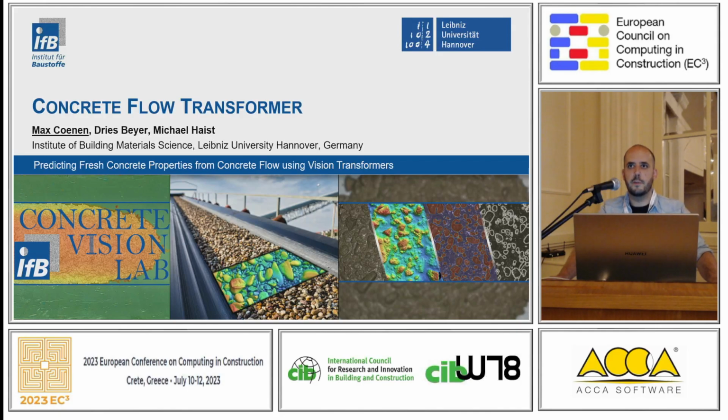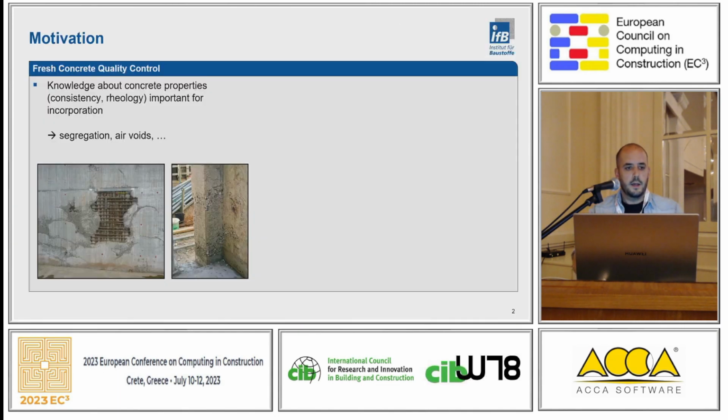Our work on the image-based and automatic prediction of fresh concrete properties from concrete flow. Fresh concrete is usually characterized in practice by its workability, a term which usually comprises the consistency of the concrete, but is also of course related to the rheology of the concrete. And the workability is a significant factor for incorporation of the concrete, as an improper workability can lead to segregation effects or air voids and ultimately to damages in the building component.